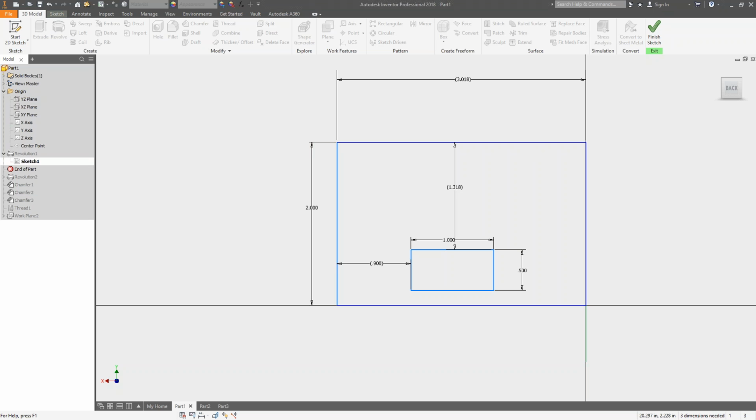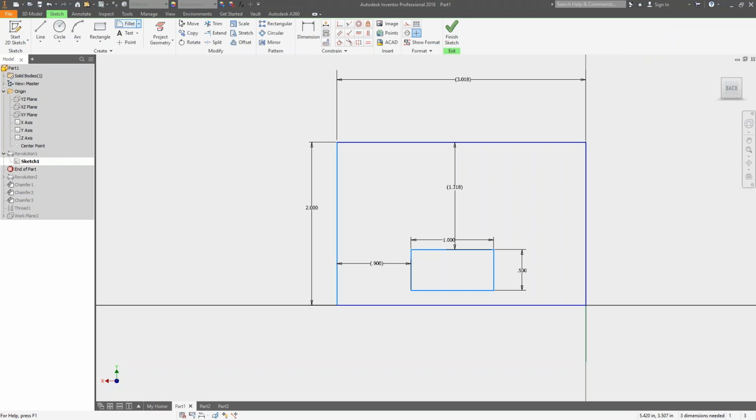Make fillet before finishing a sketch. I guess maybe, can you make a fillet before finishing a sketch? Yeah, you can. So inside the sketch panel, there actually is a fillet command, and what this does is it creates just a 2D fillet. So you just pick your edges, and it makes them tangent.